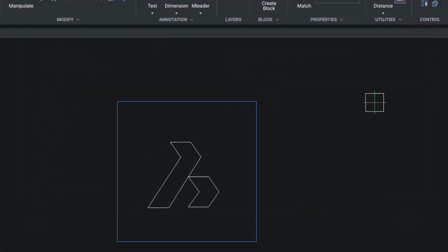I'll give the line command. Now you can see the aperture box. The program searches for area inside the rectangular aperture cursor for geometric features such as endpoint, midpoint, etc. When I take the cursor closer to the midpoint, that midpoint is snapped. And when I take it closer to the endpoint, it is identified.